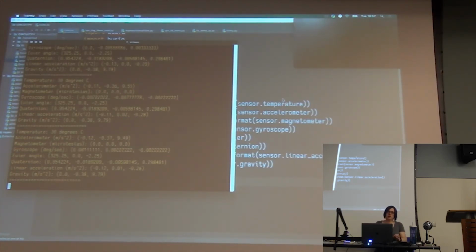In fact, we just did a library for a PWM servo motor driver chip, and we wrote a calibration test for it because if you are sending signals to those motors, they need to be accurate. To figure out what your PWM signal is going to the motors, there was a piece of code written that would send that out so you could test it, because it's supposed to be 100, for example, and if you're finding that it's 102, it's not going to be as accurate as you want it to be. So the calibration code helped you figure that out, and then you would still have to tweak your other code later, but at least you know what offset you need to set to have everything you're doing be accurate.